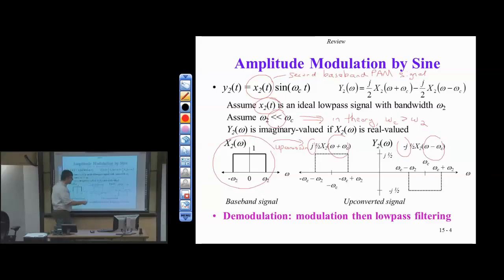We still would like a gap here between our bands. Now, demodulation follows the same approach. We demodulate and low-pass filter, and again I need to find omega c, but I've done that already to support the first channel, and I need to find the phase. Now, how do you relate the phase here on the second channel to the first channel? What's the phase difference?